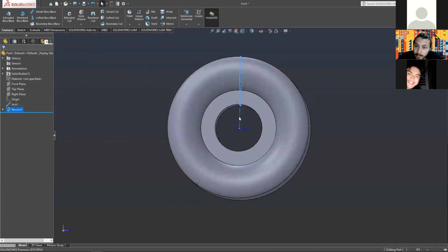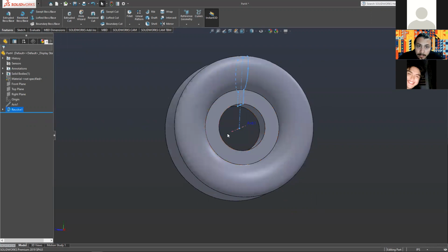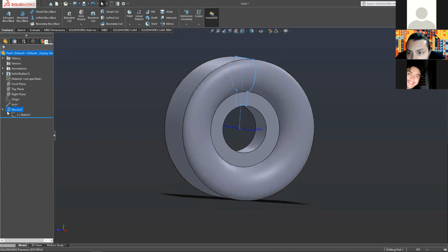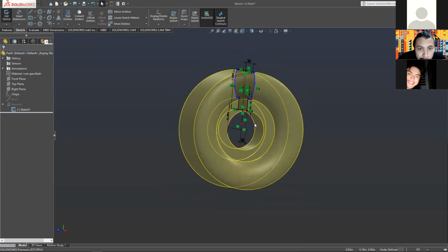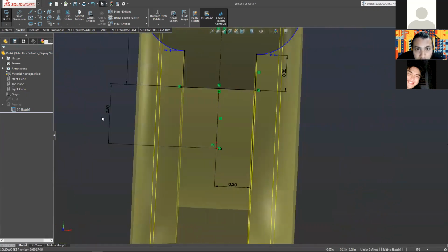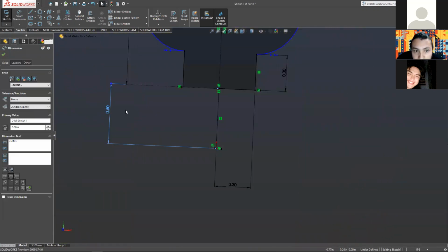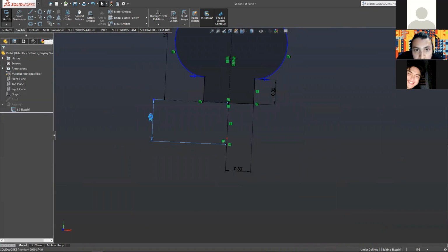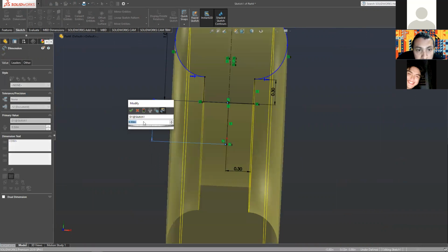We put our inner diameter as our diameter instead of the radius. When you edit that, it doesn't completely redo the whole part. Right here on Revolve 1, we'll click this little drop down arrow, Sketch 1, Edit Sketch. See, you're getting it, man. This 0.5. Why did I do 0.5? I wasn't even thinking. Double click it, and we can edit it.